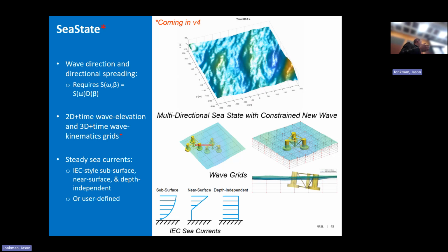And then basically now in 4.0, when you're on OpenFAST, you can say, do I want to use local instantaneous position as my turbine floats in there? You can use that or not. Basically, you can use the fixed position or you can use the time varying position. And that gets you some second order effects through that motion. Currents are very simple. It's these simple IEC steady current models.